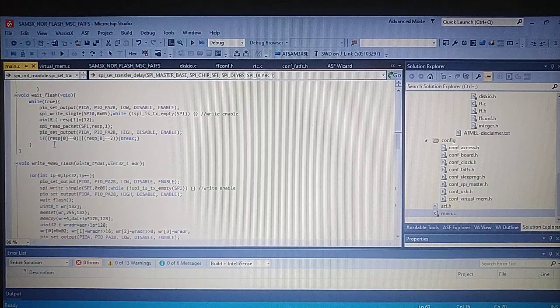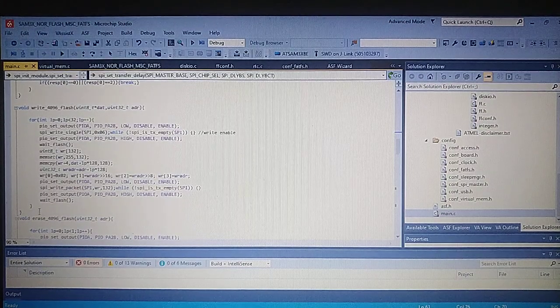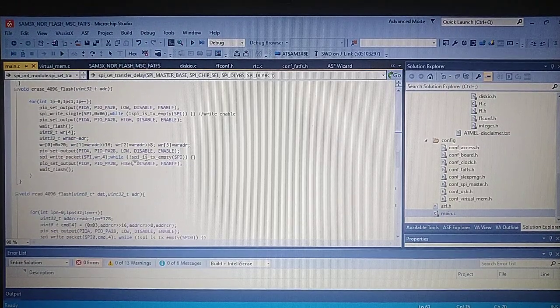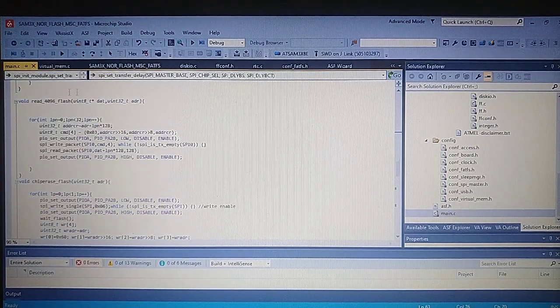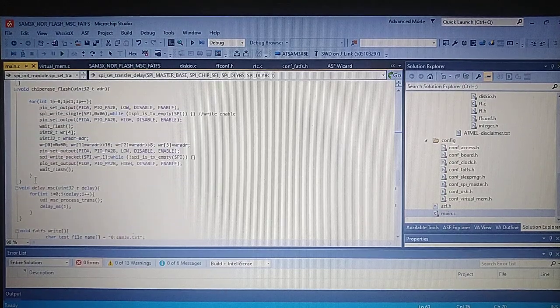Right here the function to check upon the state of the device, if it's still busy or not. We can write something to it, or we have to wait. Next, the write function for the whole sector, the erase whole sector function, which writes actually the 255 value to an 8-bit cell, the read whole sector function, and erase the whole memory.